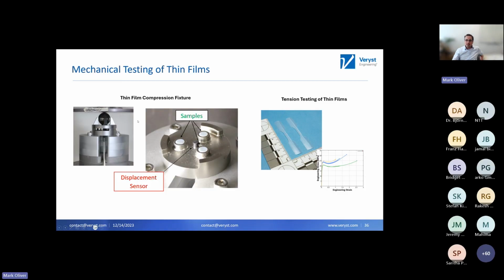And so we've used this to get at the problem of through thickness compression of very thin films. And you could do this both to get just monotonic stress strain, but also look at things like creep. So if you do have these very thin films, you may have to come up with new methods that aren't standard.